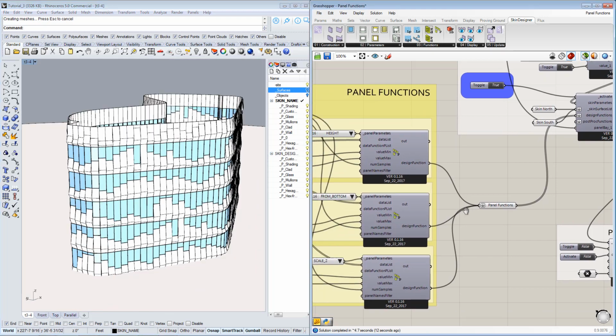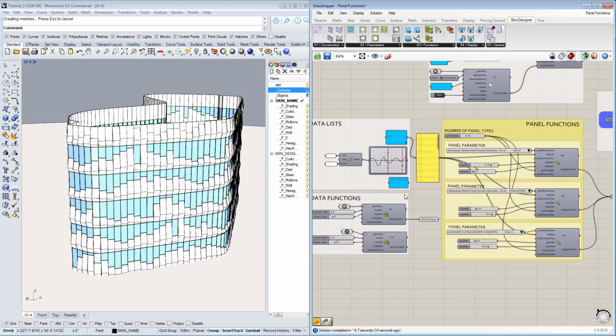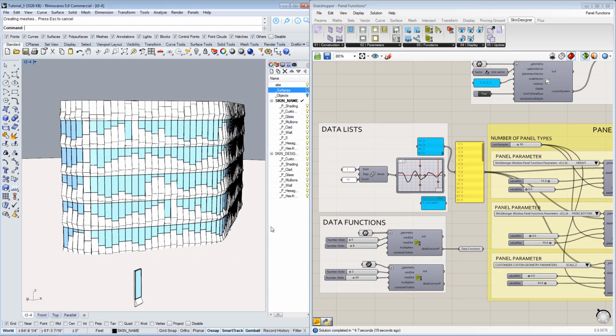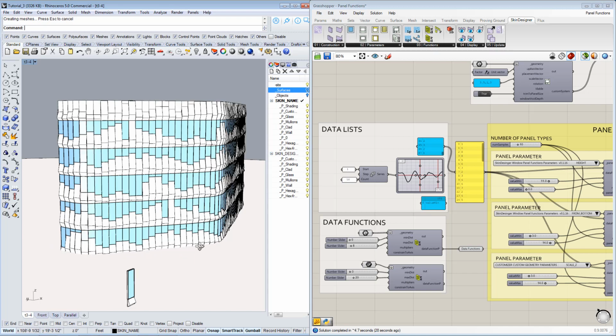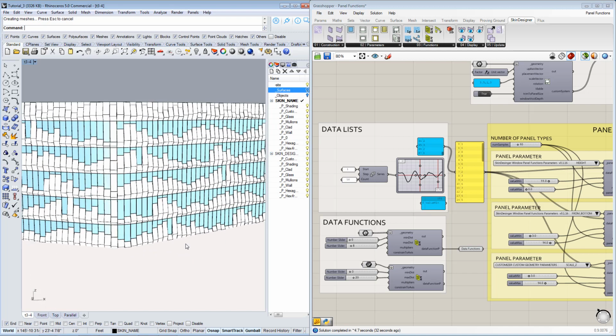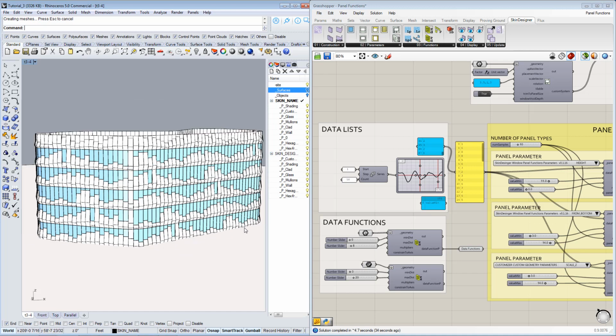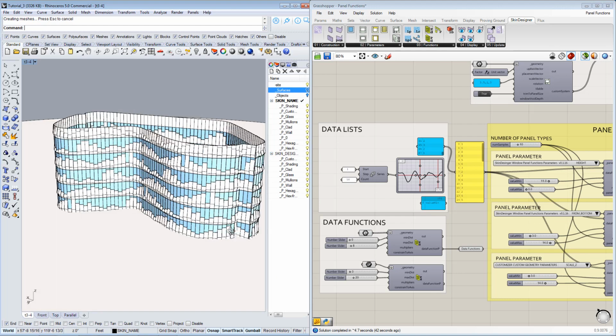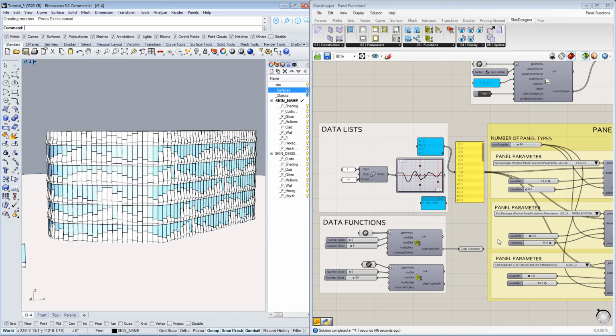All right. So at that point, this may be key to understand how this data is mapped. Basically, it starts from the first element of this facade, and it goes around along the entire row, and once that all finishes, it starts over again. So that allows you to see how that is repeating around in different parts, right? Because it's basically going from row to row with this list of numbers until it completes all the panels around the building.